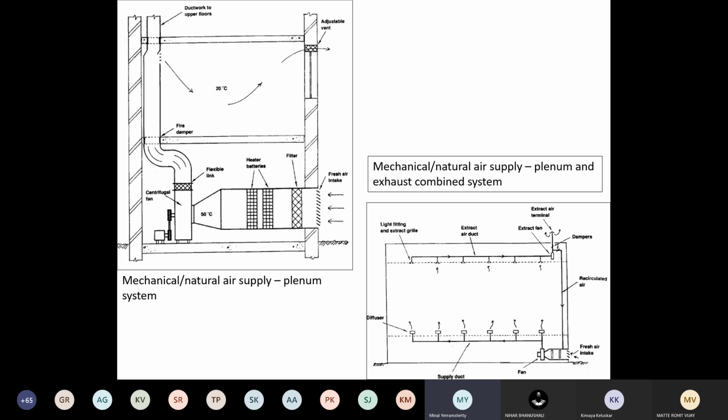In such a scenario, with such heat build-up, such a parking layout, and people also working in these rooms, one system is always inefficient, because you can exhaust, but what if outside there is no air? Sometimes you see a dead outside. There is no air outside. Then what will you do? People will be suffocating inside. So we automatically provide air by some kind of mechanical means. Worst come to worst, at least give axial fans, which will pull air from whatever little pockets are available and push it inside the basements. But if it is a small basement, as I explained, you can give either only a plenum or only an exhaust. Not a problem.